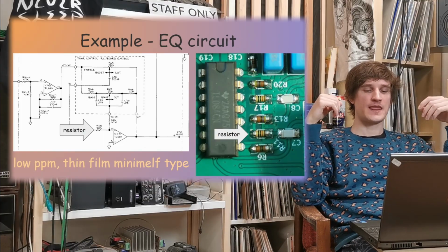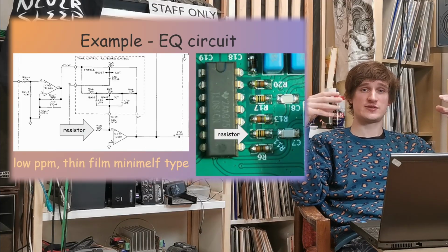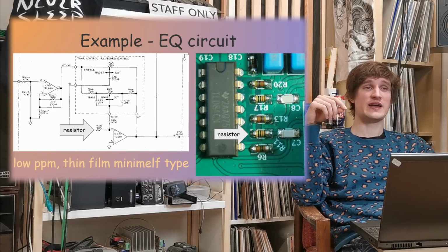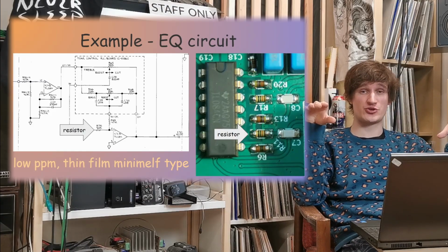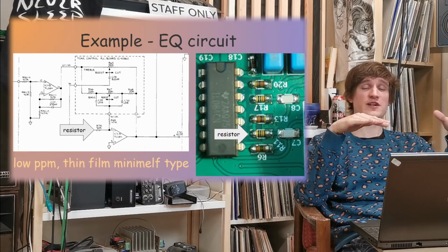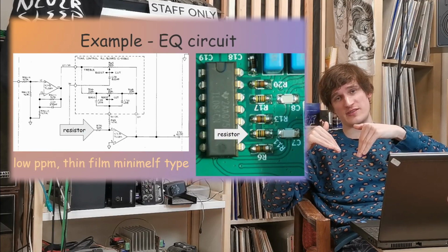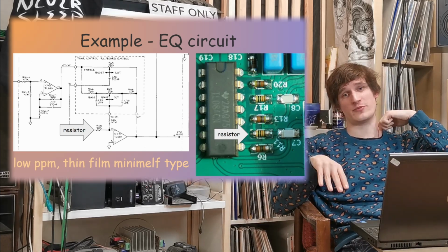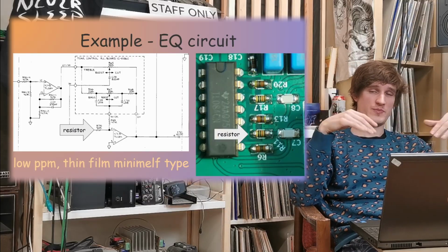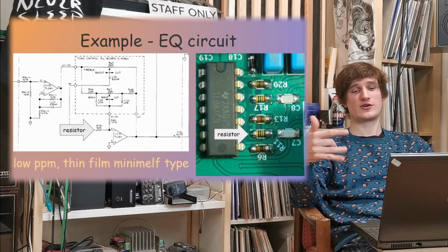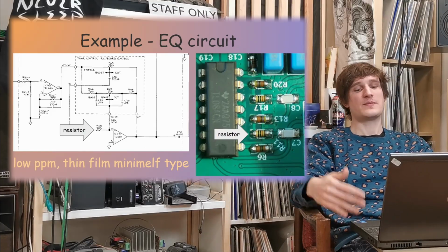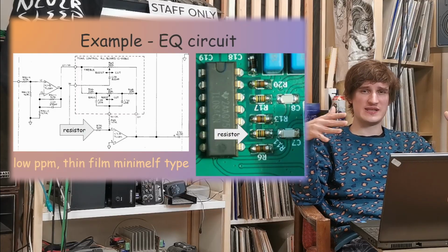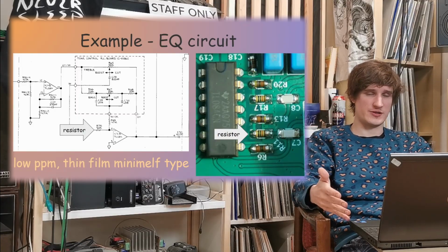So when you deal with very low distortion circuits, and I also showed you a couple of slides before this experiment from Texas Instruments, when they were comparing thick film external resistors and internal thin film resistors on chip, those thick film resistors were limiting the performance. Using low ppm resistors, you have less risk of resistors ruining the performance, but it's worth mentioning that you must really take care about it when dealing with low distortion circuits.